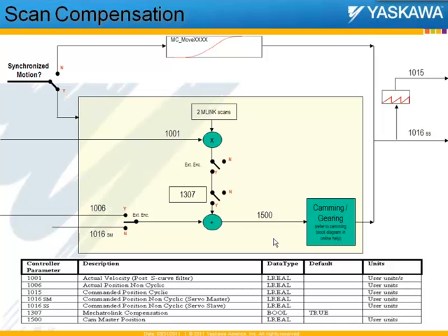This is forward compensation from the controller into the servo pack, and it gets added onto the command that goes into the camming or gearing algorithm, and the slave data gets the final compensated position, which is shown in parameter 1015 or 1016. Once again, this block diagram will be available in MotionWorks IEC 2.0, the PLC Open toolbar, PLC Open help, online help in MotionWorks IEC 2.0.